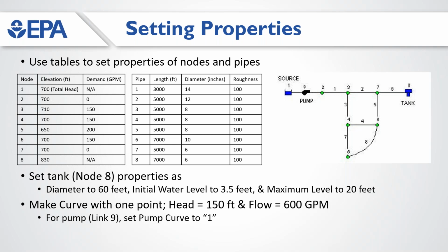For the pump, we will first create a pump curve, and then we'll assign the pump curve to the pump. And now I'll show you. This video is longer, but I'll show you how to do it and try to follow along in EPANET. I'll have these properties on the side of the screen so you can go at your own pace.